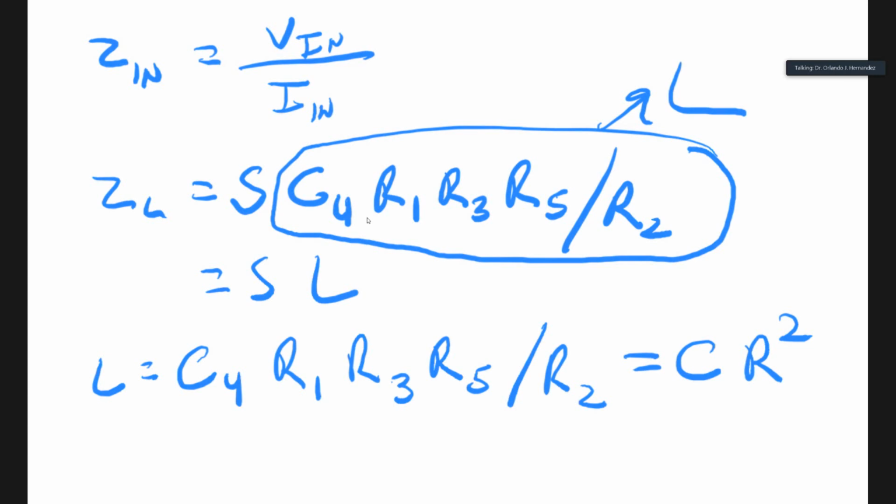And now, if I wanted to build a filter, because the inductance simulator has op amps by default, it becomes an active filter. I can use it with the prototype of the LCR resonator in place of the inductor, and then I can get a second order filter based on that prototype. Okay.